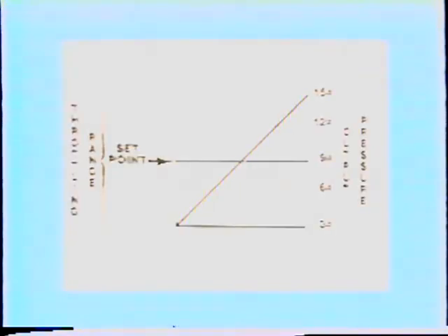The integral relay is designed to overreact to the offset of a controlled variable. As the proportional controller senses a change in the controlled medium, it changes its branch line output pressure proportionally. The integral relay is factory calibrated to look for a 9 psig signal from the controller it is monitoring. As the branch line pressure of the controller drops below 9 psig, the integral relay decreases its output and continues decreasing its output until the branch line pressure of the proportional controller returns to 9 psig.